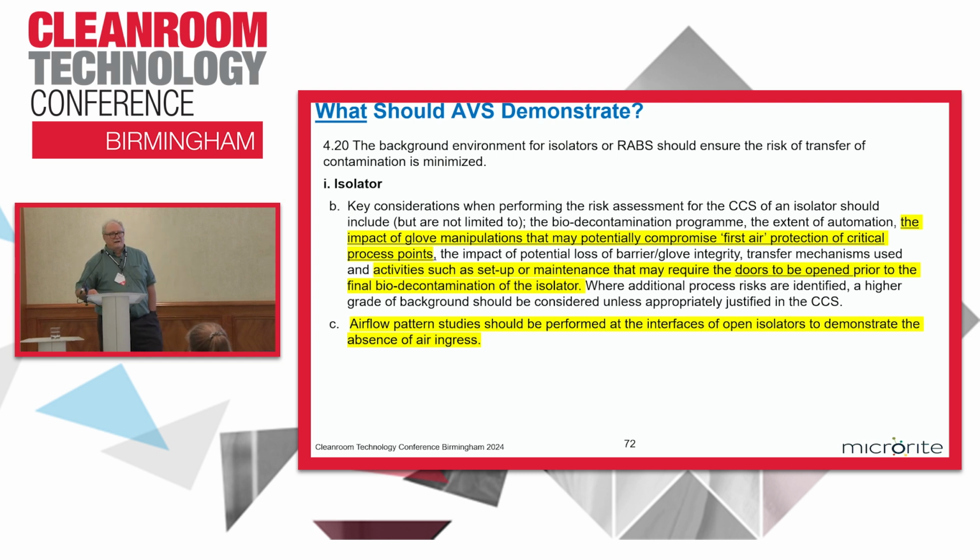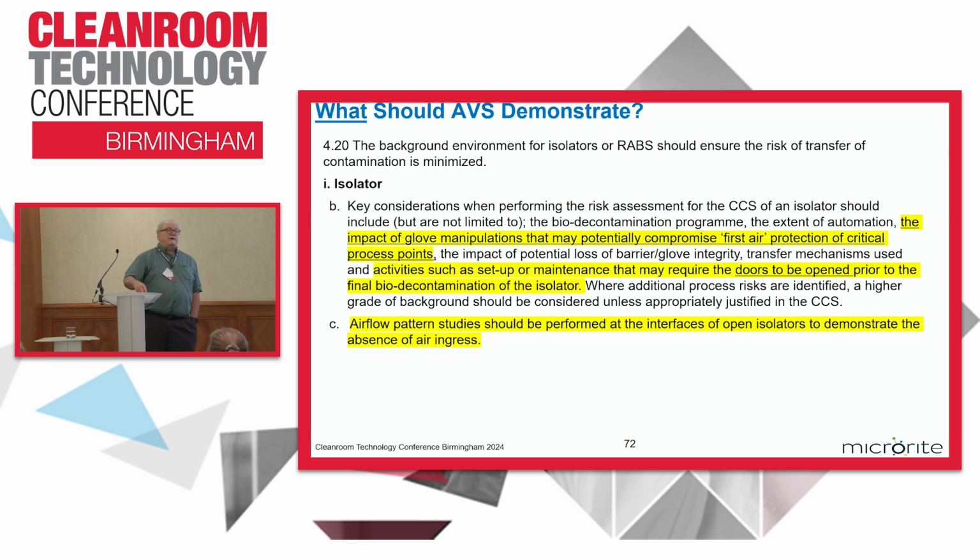Understand that. Because multiple times, U.S. inspectors and foreign inspectors have flagged people we've worked with, saying, hey, we don't like your hand sanitizer. It's inconsistent. One facility we did recently, two-operator intervention. They had multiple two-operator interventions. One operator would wear his gloves over the sleeves of his building suit.